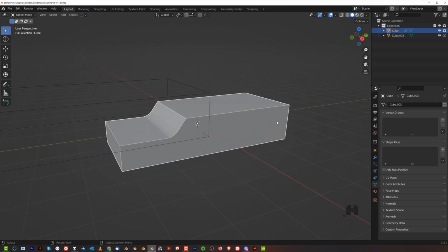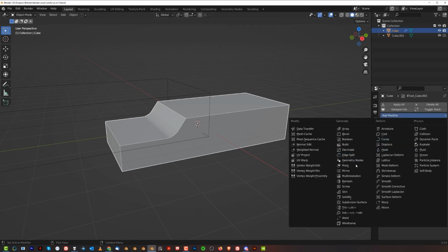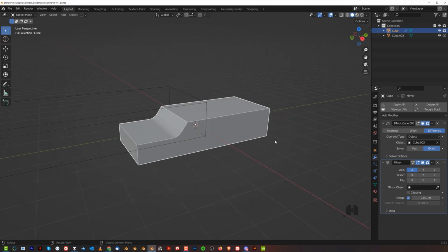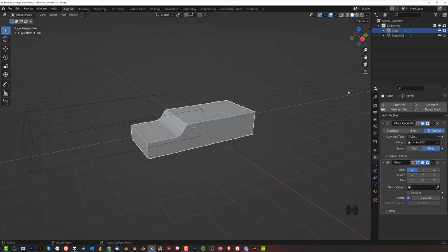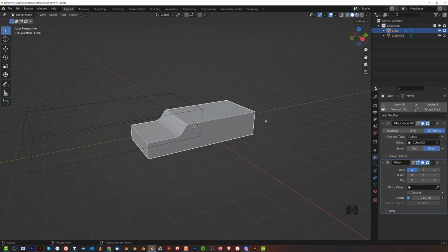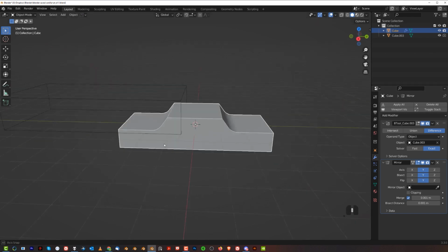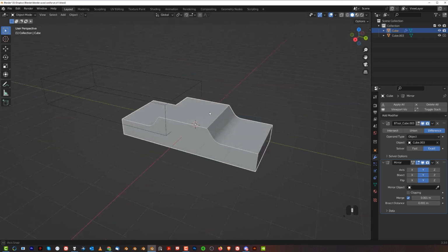I'm going to click on that mesh, and click on the wrench. We're going to add a mirror, because we want to mirror this cut to the other side. So click on the mirror, and now we need to mirror this across the Y-axis, this yellow one, right? That's X, that's Y, and the Z. You don't see the Z-axis, but I can enable it in here. That's the Z-axis, okay? By default it's disabled. So here we're going to remove that rubbish and just press Y, bisect and flip. And this is going to flip this to the other side, okay?